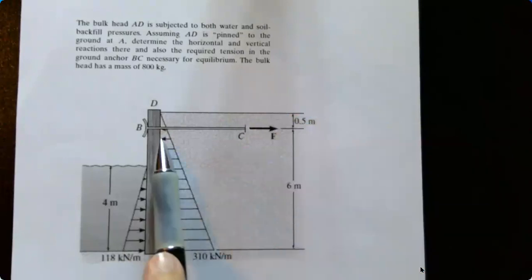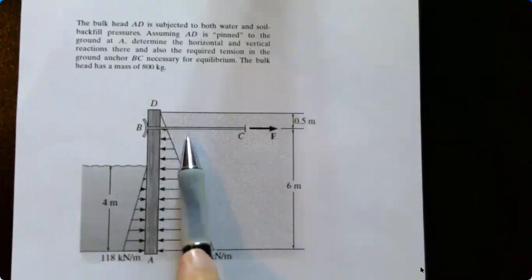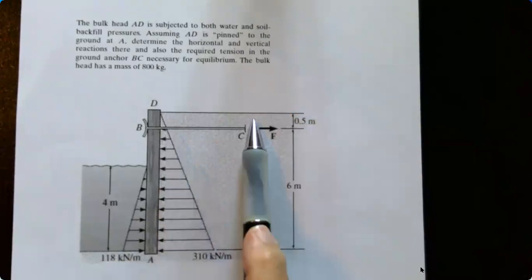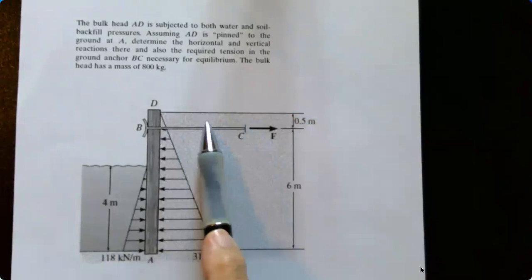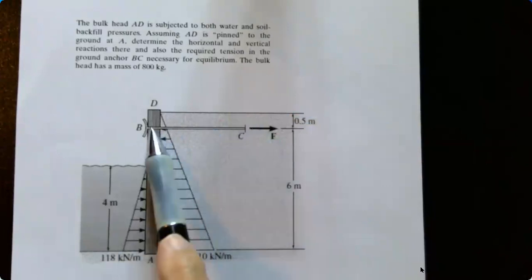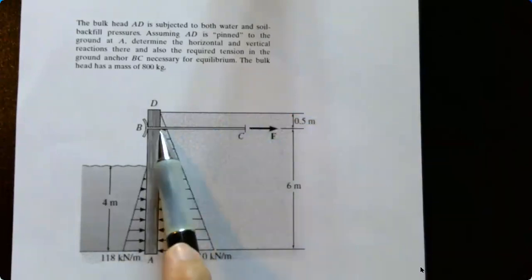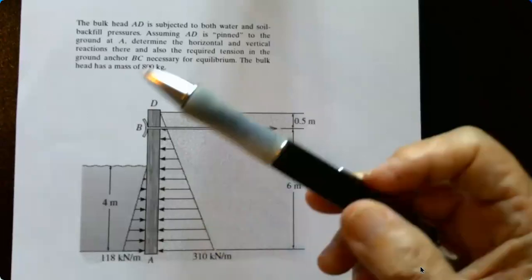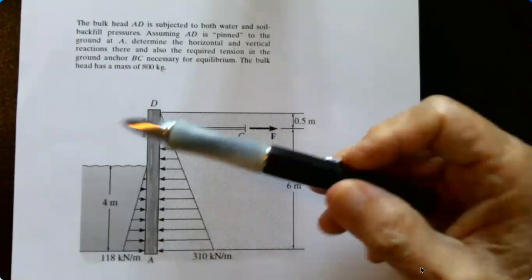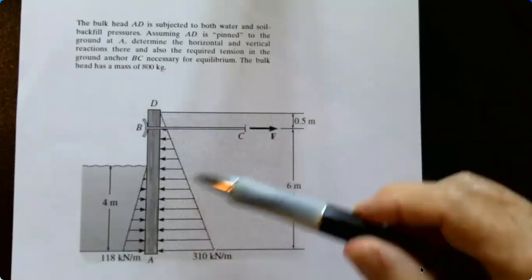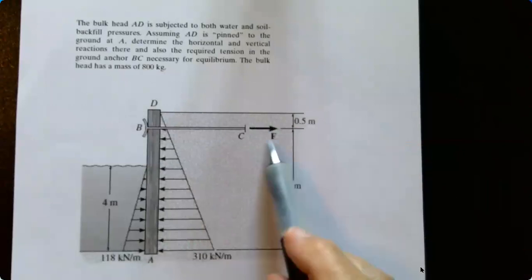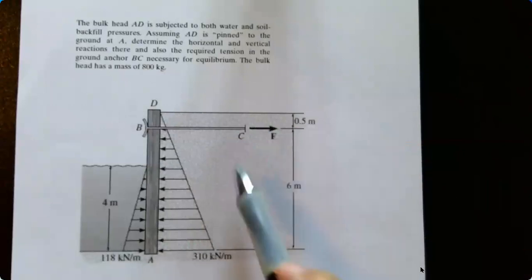you can place in here these structures which are anchors, soil anchors. Okay, call them ground anchors. They're both appropriate names. So these are ground anchors that would probably be positioned linearly along the length of the bulkhead to provide an additional reaction against the soil pushing out.